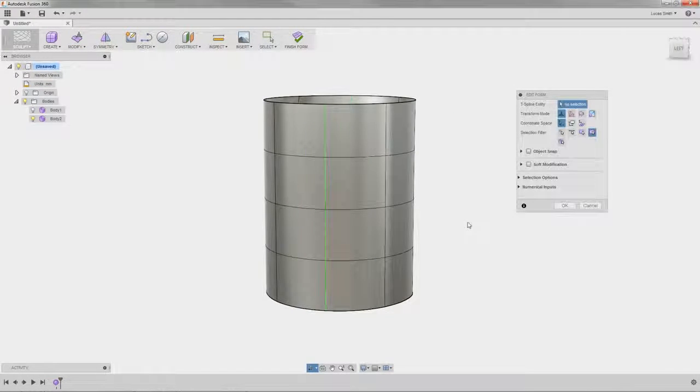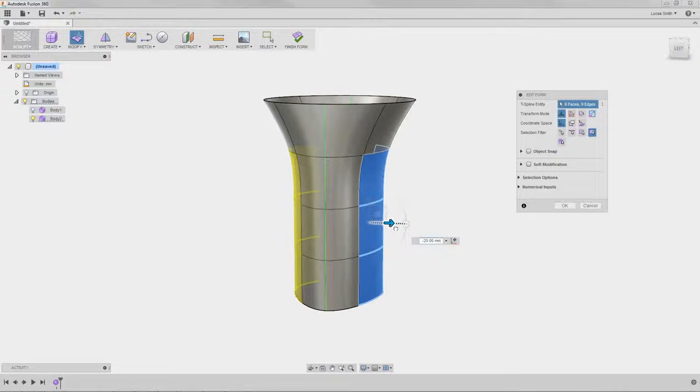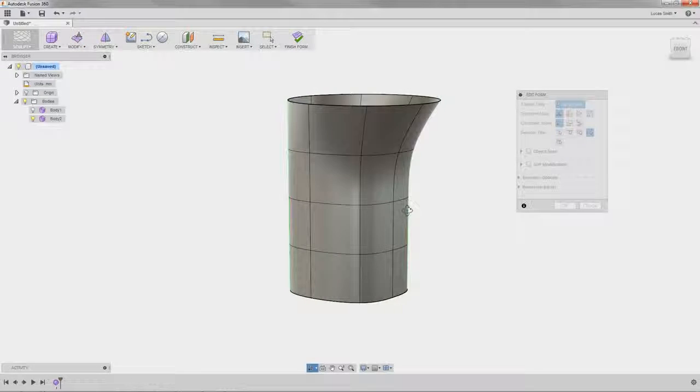If the geometry of the shape is too simplistic to create the details you want, add edges and points for flexibility and control in editing. T-spline technology lets you create bodies with edges that are perpendicular to other edges, as opposed to only allowing entire loops around the perimeter of the shape. I'll add a few edges at the front of the model, so I can refine a more detailed area of the model. Remember that adding local detail only where you need it is the best way to create a shape.